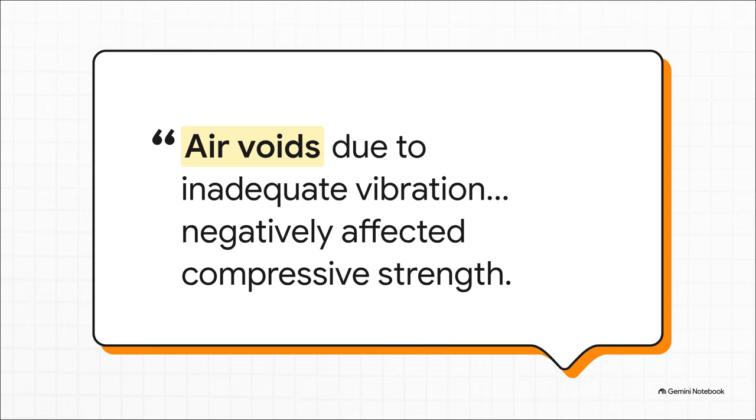Without proper compaction, trapped air voids just sit there inside the block. These voids act as major weak points that will drastically reduce the concrete's ability to withstand pressure. That compromises our test, and in the real world, it compromises the building itself. So wrapping up Section 3, proper casting and consistent water immersion are your absolute pillars for successful curing.